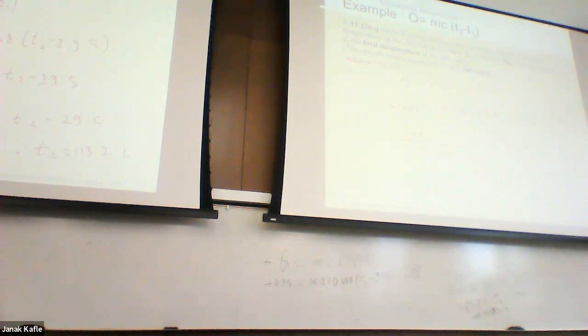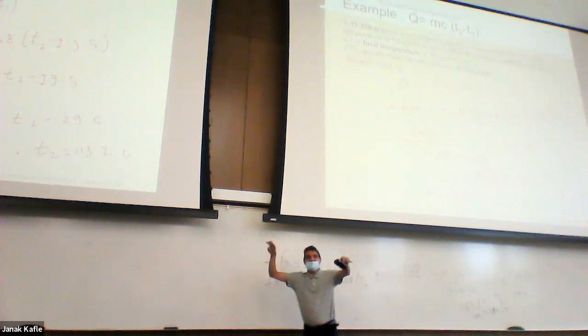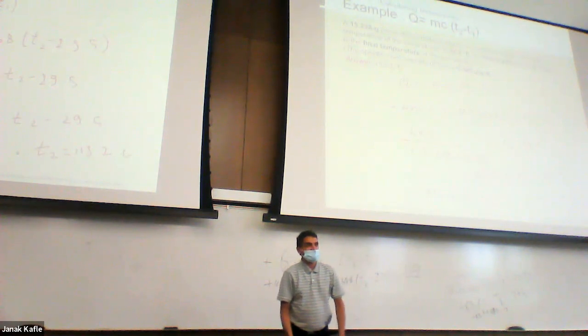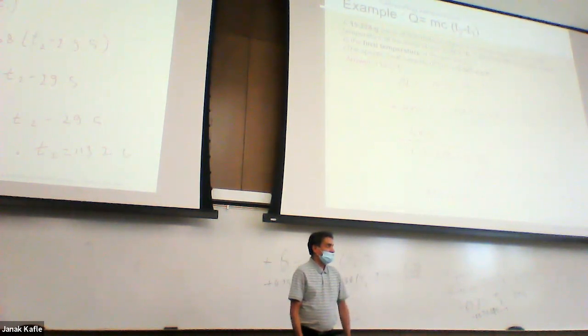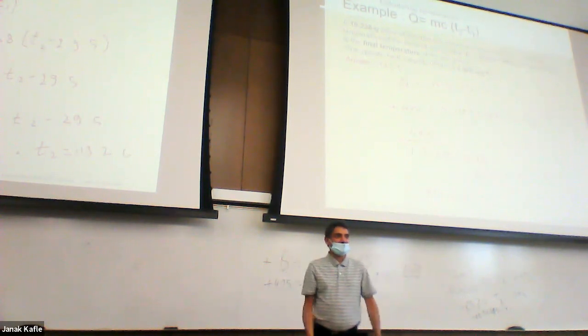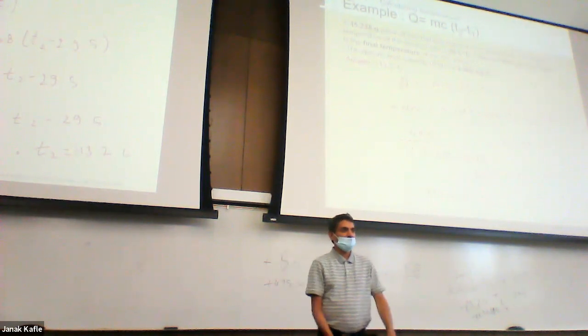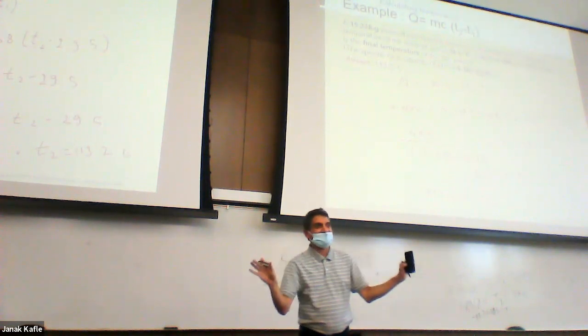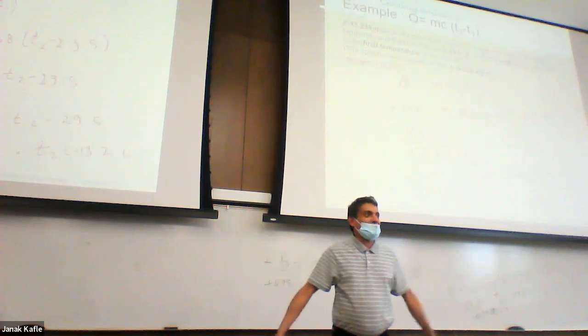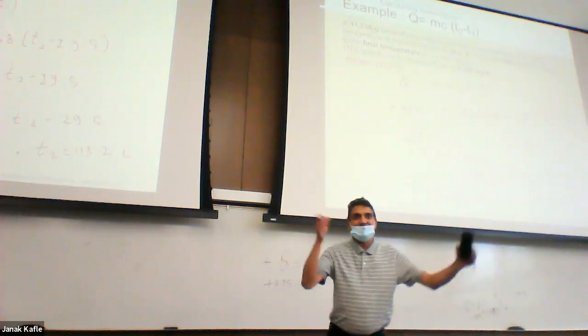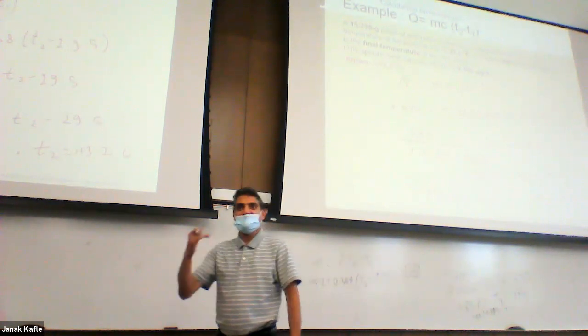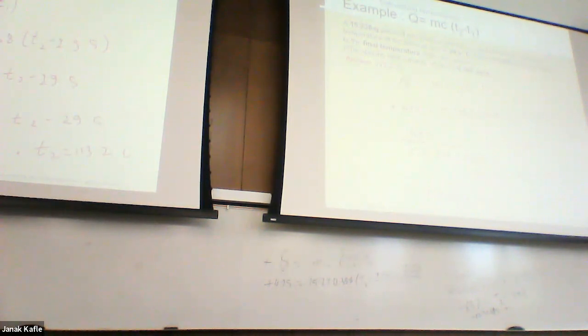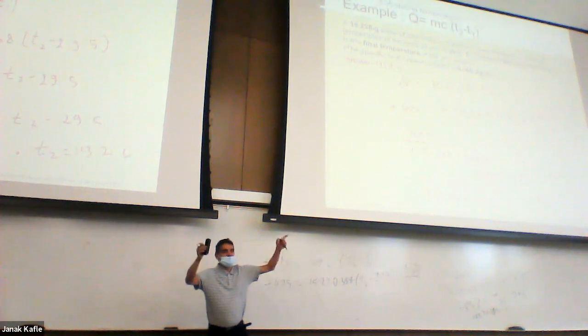This is pretty simple, but later on, if something is losing heat, we should be putting minus here. If we don't put minus or plus while doing the temperature calculation, we will easily make a mistake. If something gains heat, the heat value should be written as positive. If it is losing heat, the heat value should be written as negative while we are doing the temperature calculation. But when you are doing the mass or specific heat calculation, although a minus sign comes there, you can easily say, oh, mass cannot be negative, specific heat capacity cannot be negative, so you can just write whatever you like. But while doing temperature, I would not make a mistake because I did this kind of problem a long time, so I know what is going on. But you can get easily confused. So the best way is if something is losing heat, write minus here. If something is gaining heat, write plus here, and that way you never make a mistake.